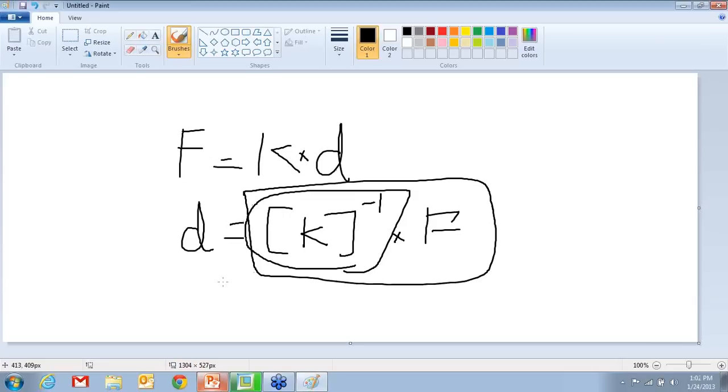So by default, a K matrix is singular. When you add constraints to your model, certain rows and columns in the matrix are removed and it becomes non-singular. When it's non-singular, it becomes invertible. Fair enough? And hence you solve it. So most of the times your errors are also like insufficiently constrained. When it's insufficiently constrained or some of the elements have a problem, you cannot go back and look at the matrix, which is about 1,000,000 by 1,000,000, and find out which particular area has a problem.